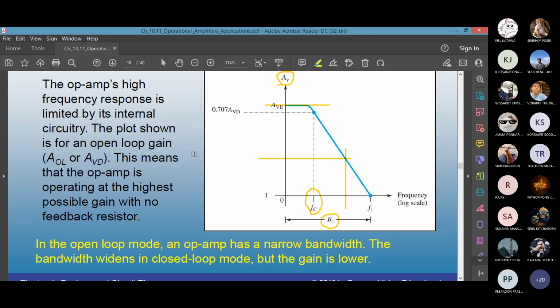Op-amp is a low voltage application. If you have, let's say, 0.1 millivolt and then you have open loop gain of 20,000, that's okay. You're going to get an output of 2 volts. That is within the tolerable range. But in real life, our circuit input is not half millivolt or 0.1 millivolt. To operate in real life, you have to think of realistic values.